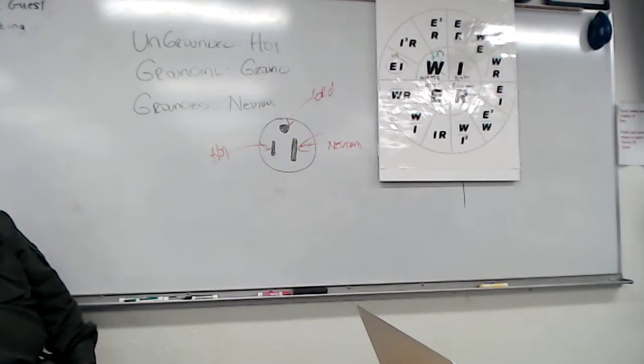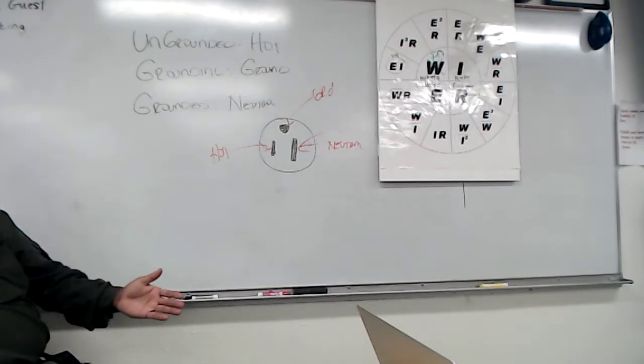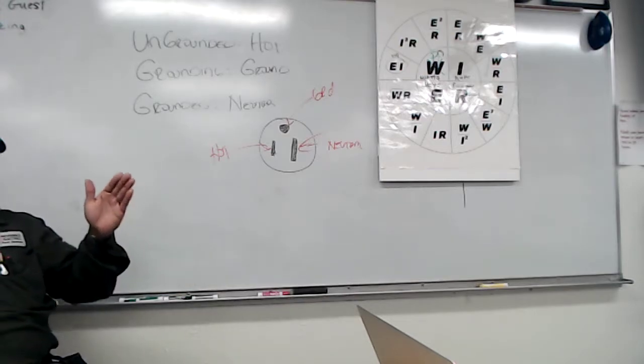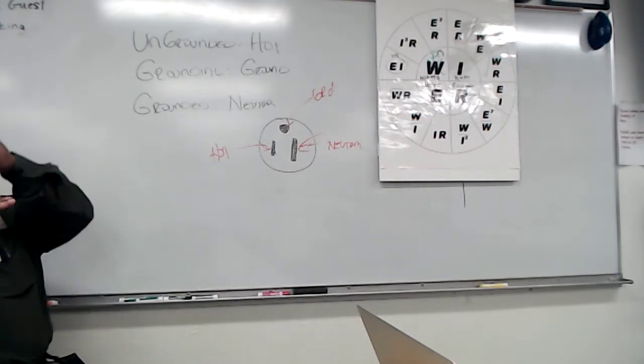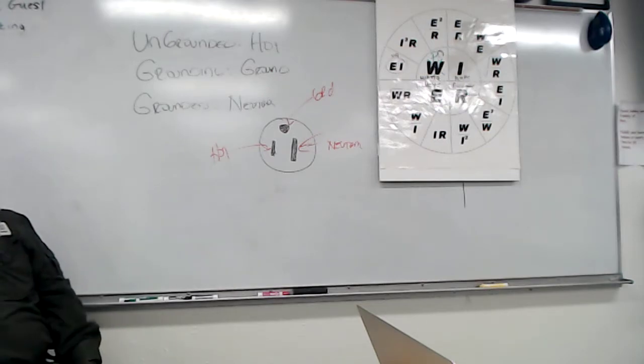Why do they install some of the receptacles with the ground up? The theory is, and I've had this happen, a client whose kid dropped something across a plug and pulled it out halfway. Then she dropped something else behind it and went across the hot and neutral and shorted it out. If it's upside down, that'll never happen.